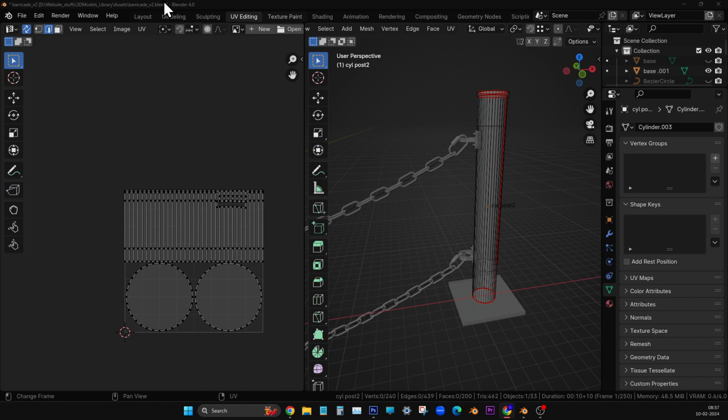So Alt A, and now you can select all. You have to press Control Space. Right. Now press A on the keyboard. Now again do the UV unwrapping just for refreshing. No, you are doing it. Okay. Press U, and then UV unwrap. Yeah, that's all. Right. So same thing I will also do.